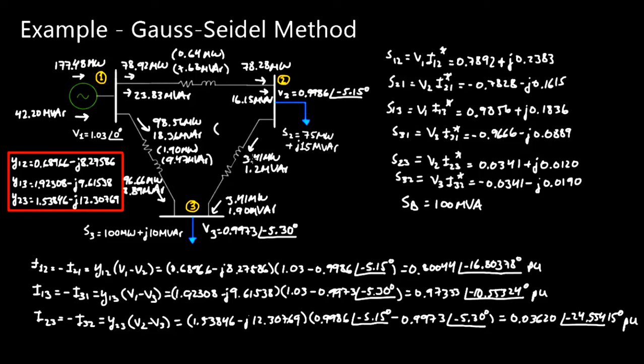It's just that when we round to 2 decimal places on a megawatt level, we don't see that loss. And so I'm going to put it here 0.00 megawatts, but just know that there actually will be a loss in the transmission line. We just lost that accuracy when we're rounding to 2 decimal places, and especially on a megawatt level. So if you think about it, 0.01 megawatts is 10 kilowatts, so that's a significant amount of power. And then we also lose 0.01 megavolt ampere reactive.